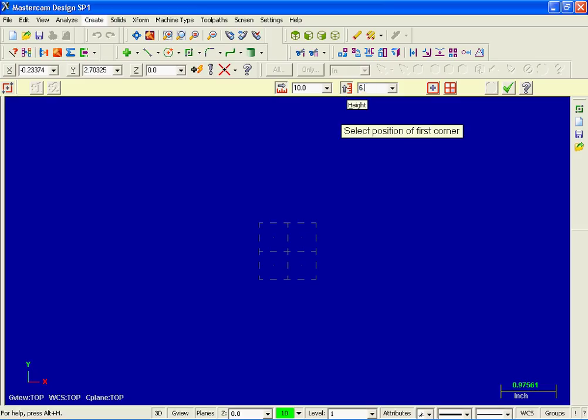the height is 6.0. Now as we slide over to the right, I'm going to activate Anchor to Center. So my anchor point is in the center of this rectangle. Now I'm prompted to select position of base point. Well, the base point is at the origin X0, Y0, and as you can see, the visual cue on the screen is letting me know that I'm going to snap to the origin. So I'm just going to click this point. Now we've created our rectangle.